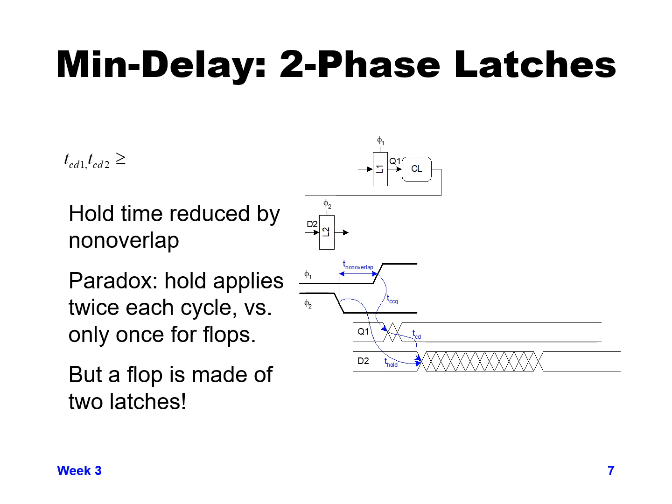Now let's do the same min delay analysis for two-phase latch design. So in this case we have a phase 1 latch L1 whose output is Q1. Then the delay goes through the combinational logic, goes to D2, whose input is to a phase 2 latch. In this particular case, you can see when the phase 1 latch, the clock goes high, it opens the phase 1 latch. We get a contamination delay, the fastest delay from clock to Q1 that we can get.